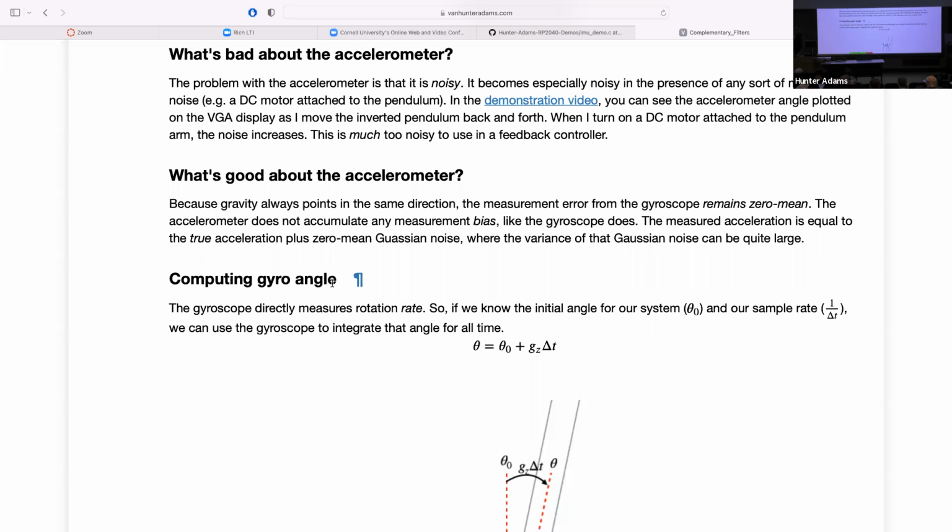It is noisy, yeah. So it's just to get you in the ballpark, right? And then because you are high passing the gyro and low passing the accelerometer, it corrects itself and you end up with complementary filter outputs that are better than you could get from either the accelerometer or the gyro.